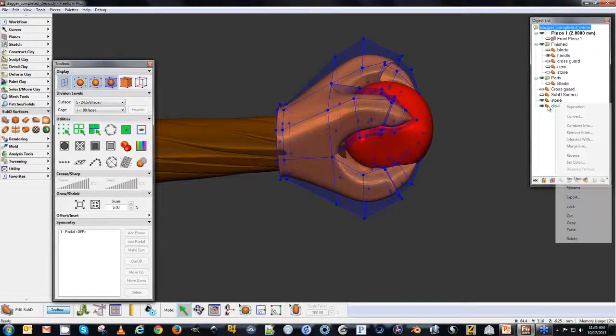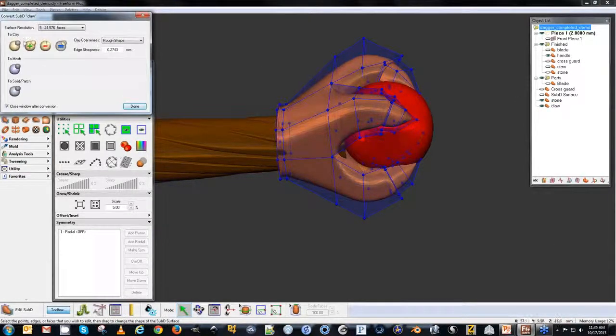That was my fault, because when you go to convert the surface resolution, which is only divided down to where this is showing 24,000 faces, I can dynamically change this at the time of export to refine the surface, so I don't have to work with all those polygons while I'm working. So now I can change this, drop this down to clay, and continue working with any of the tools that I would normally use for clay sculpting or any type of voxel operations on it.